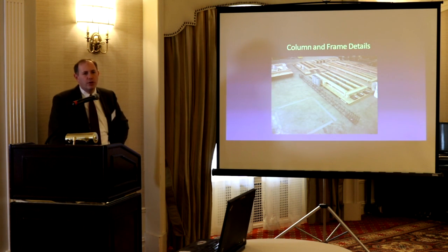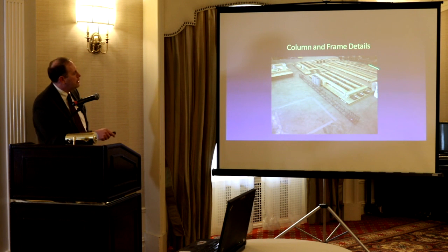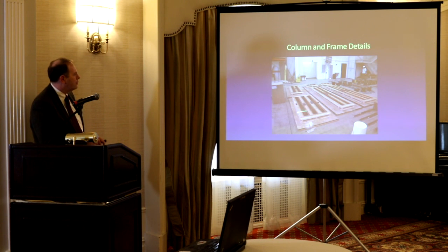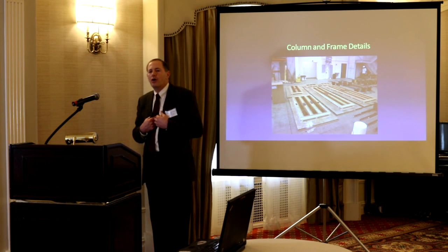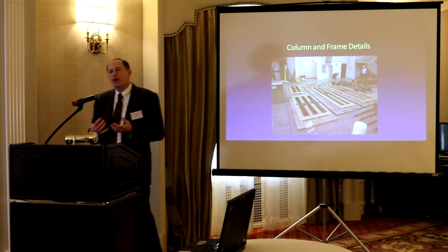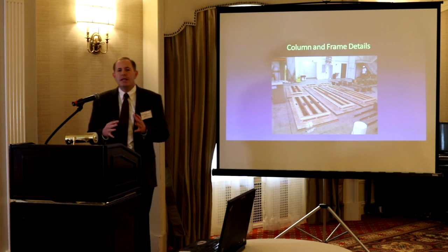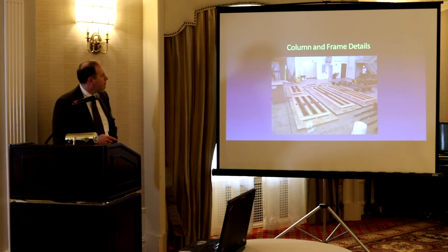Here are some images of the lab when we're casting them. So these are the different columns, and you can see the cylinder there to get a little bit of a sense of scale. They're reasonably sized, and then we have our ties. So here's the bed there before. You'll also notice we did some short columns too. We calibrated some of our creep and shrinkage that's occurring relative to short columns that didn't have second order effects.